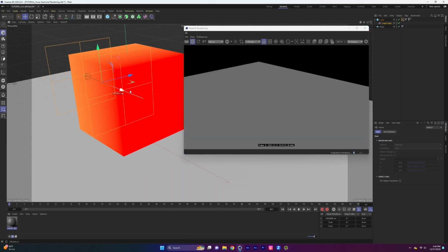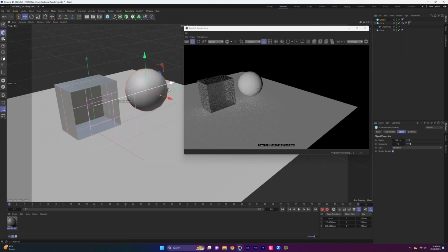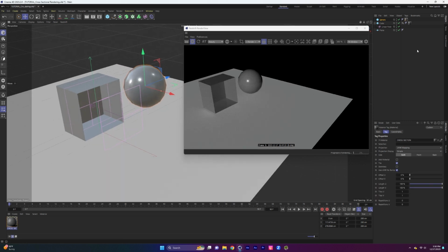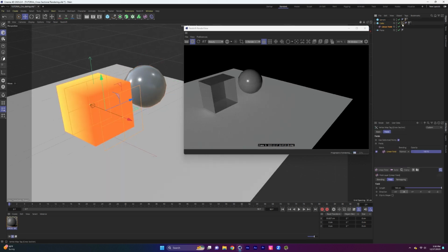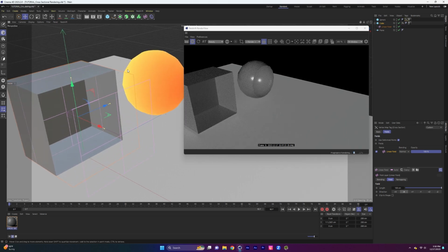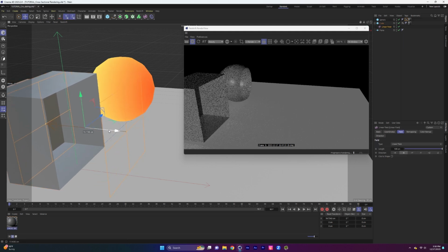So if you wanted to cross-section another object, for example, this sphere, simply drop the material on it, control-click and drag the vertex map tag to copy it to the new object, and boom. You're now controlling a cross-section of both objects with one linear field.